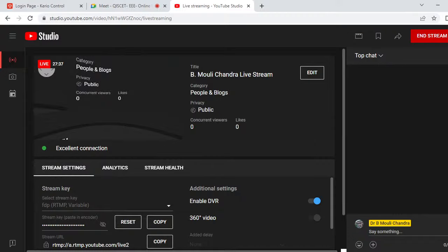In case 2, we have considered 3 DGs operating at unity power factor and 3 shunt capacitors injecting reactive power, placing the 3 DGs and 3 shunt capacitor banks simultaneously. In case 3, we have considered 4 DGs and 4 shunt capacitors simultaneously, and in case 4, we have considered 6 DGs and 6 capacitor banks. Here the number of DGs is chosen depending upon the total load demand plus the reactive power loss and real power loss of the line.